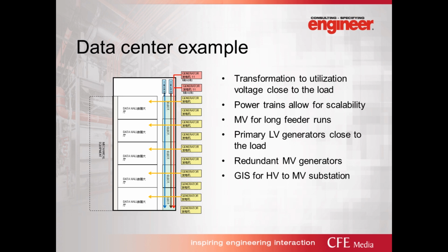This particular site also had gas insulated switchgear on the high voltage side. Land was very scarce, so we used gas insulated switchgear on the high voltage side just to reduce space from those big, large open air facilities.